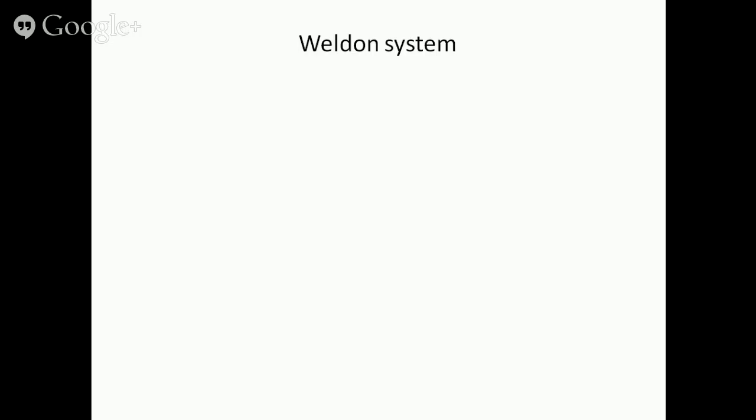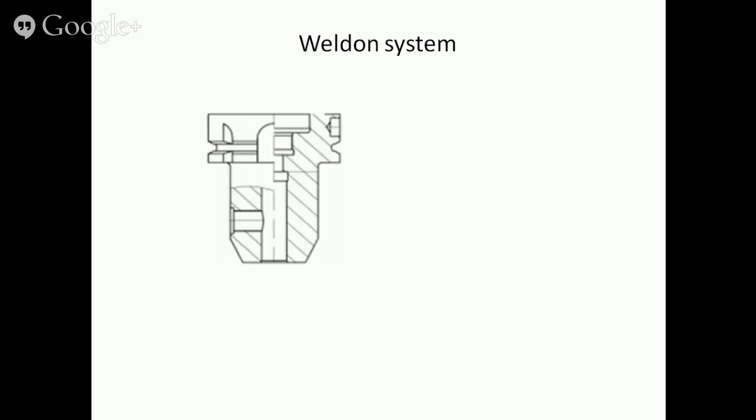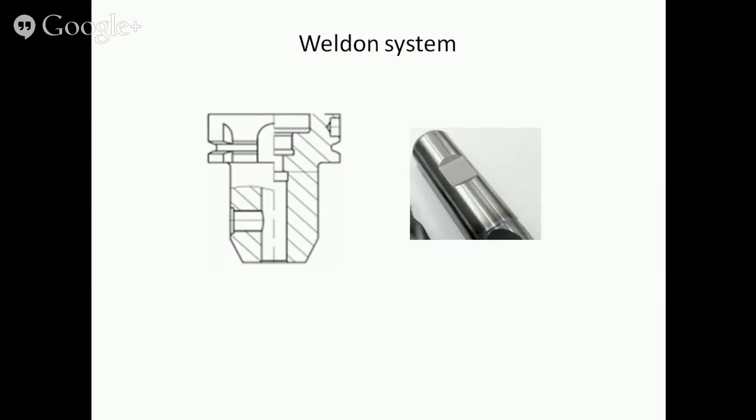For heavy-duty performance of cutters with cylindrical shafts, the Weldon system is indicated. Weldon cutters have a flat surface to which the locking screw is fastened. The V-groove is explained later.